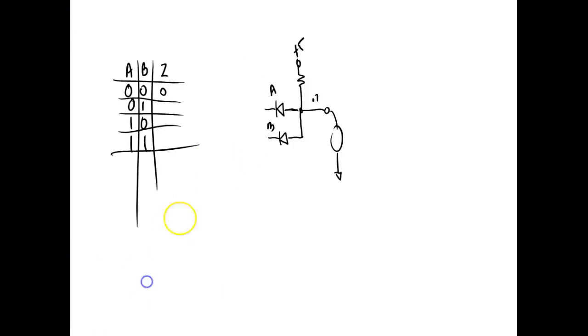Good, guys. So I'm going to come up here now, and I got it backwards from a while ago. I'm going to make A a 0 and I'm going to make B plus 5. What would the output be? This guy's turned on. When it turns on, it's effectively bringing this 0 and putting it right there. Actually, it'd be a 0.7. So that's going to put a 0.7 right there. So now the cathode is positive in respect to the anode. So this guy right here is going to turn off.